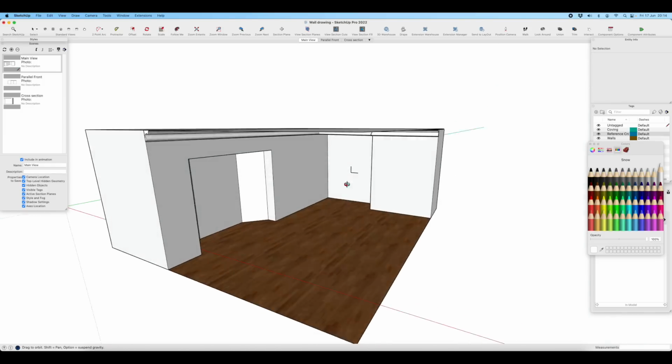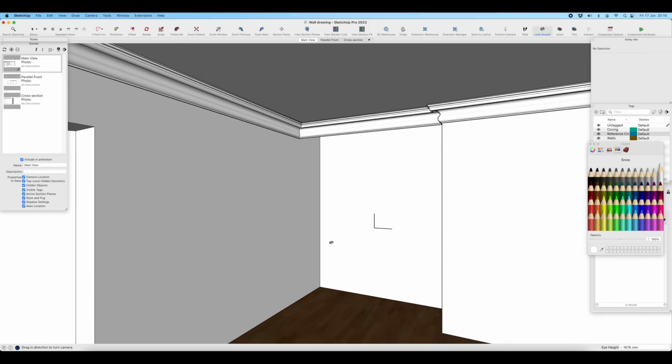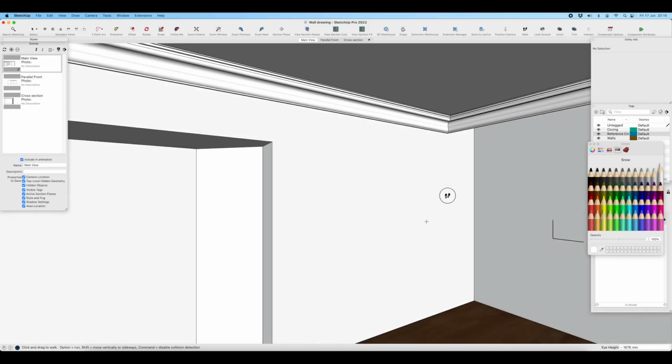And if you want to be really accurate with a final camera position, this position camera tool will actually position the lens of the camera at head height off the floor. I think you can set that height as well in the settings or in the preferences, and then if you use the walk tool you can walk around in that direction.